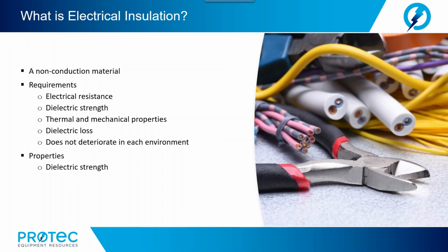It deteriorates with the ingress of water and with elevated temperature. For high voltage applications, dielectric strength is the most important single property of the insulation. Insulation resistance is a measure of how much current will be drained away from the conductor through the bulk or along the surface of the dielectric.